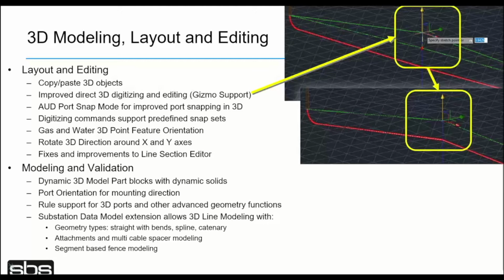And the way that system works is that as different sizes are specified for a particular feature, so you could place some type of supporting structure or some other type of structure that has a specific size, set its height, width, or other values. And then as those specific dimension values are specified for that, the system will go and take that dynamic block and sort of generate a specific sized block for that.